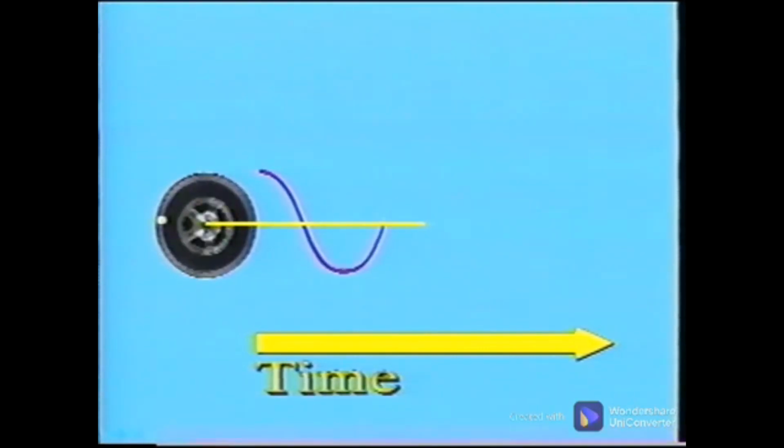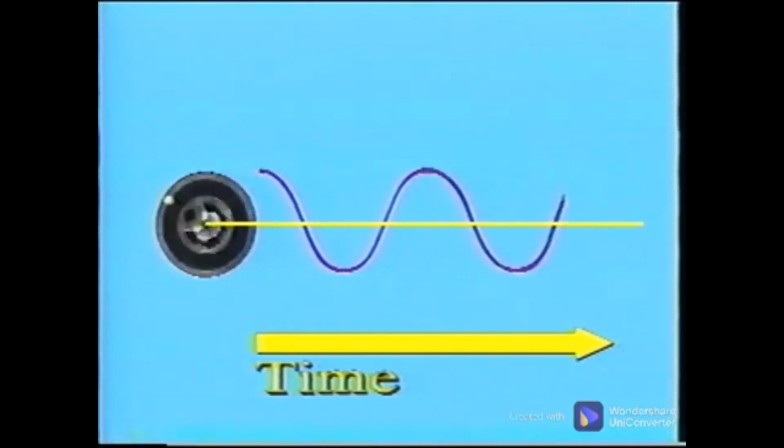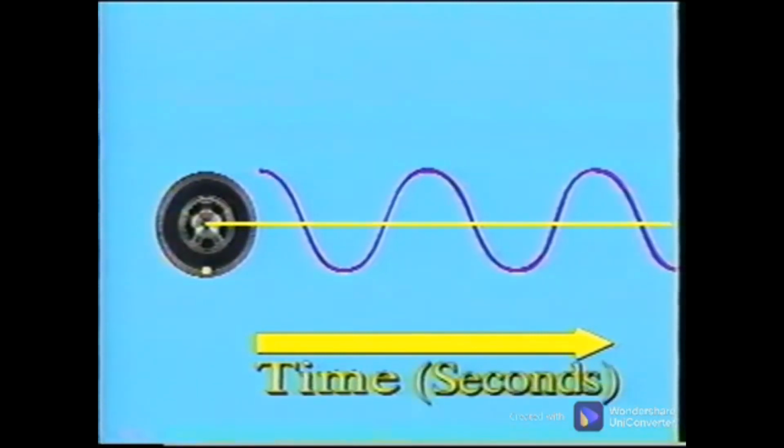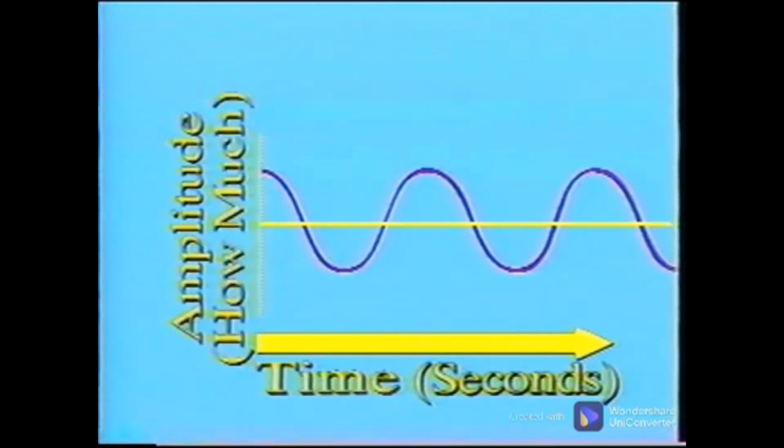The trace of the unbalance has now moved up to the center line of the tire, but is still to the right. The tire completes one revolution so that the unbalanced weight is at the top. This then is the trace of the path the unbalanced weight makes during one full rotation of the tire. As the tire continues rolling down the road, the trace repeats the pattern for each revolution or cycle. The horizontal or x-axis shows the time it takes to complete one cycle or revolution. The y-axis shows the amplitude, or how much the unbalance moves during each rotation.